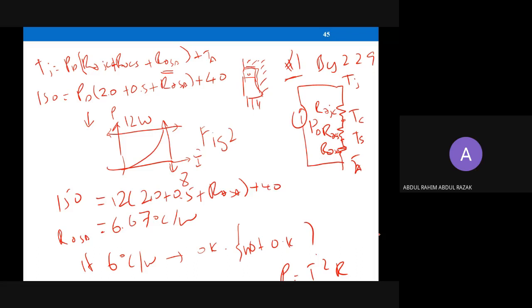Yeah, IRF 630. Okay, take note that different manufacturers may retain the same part number. But if you take a look at the dedicated datasheet, there will be distinct differences in terms of resistance, performance, and limitations.